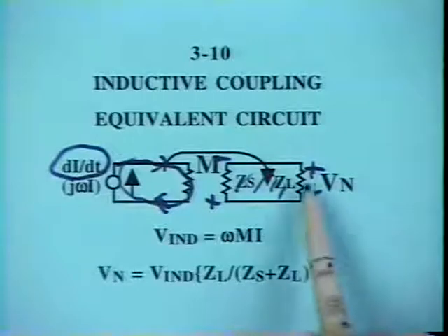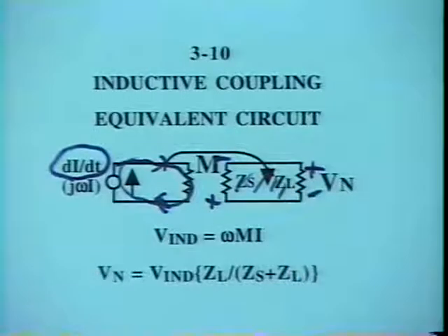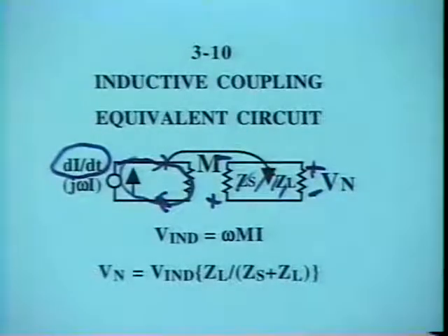Now in this case, we're looking at the load end. The load end of the circuit is where we're typically measuring the signal. If the noise produces the greatest contribution at the load end, that's where it's going to be more detrimental to us. So it's the impedance at the load end of the circuit that is critical here. The higher the load impedance is, the greater voltage is developed across that impedance. The impedance on the source end is of lesser concern to us.